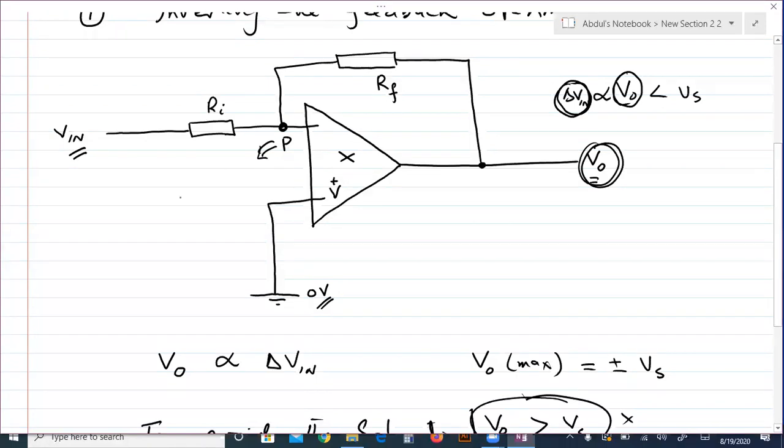Then one of the input voltage is 0, so keep the distance low. This P must be at virtual earth potential, because this is 100% at the earth potential. We will keep this P close to 0, and close to 0 mean virtually earth potential.